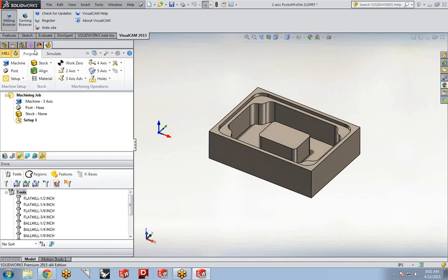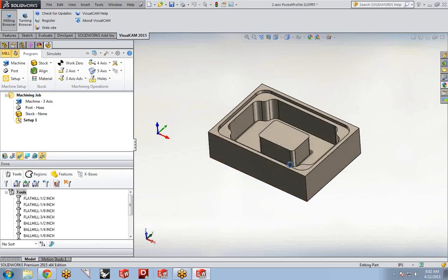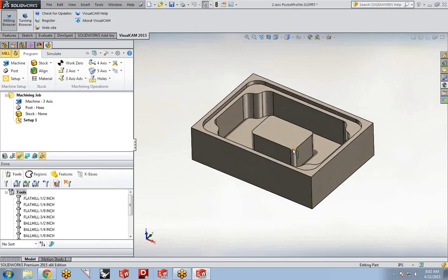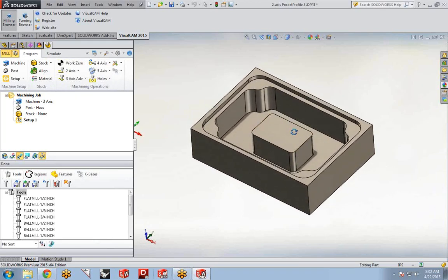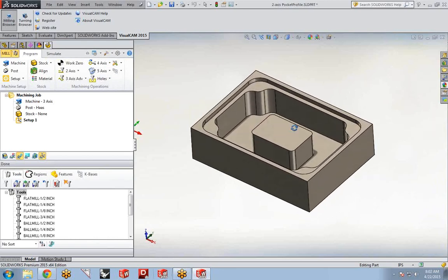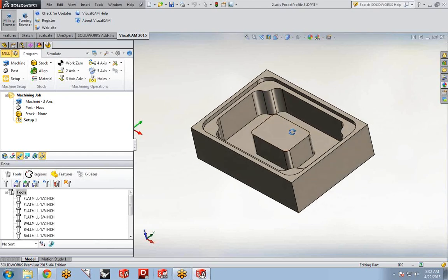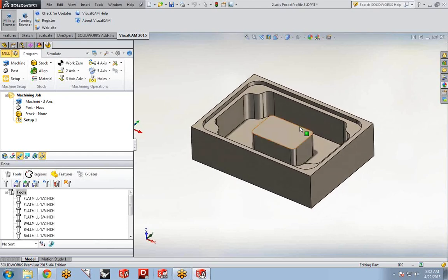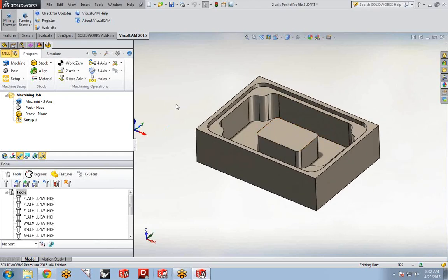First, we'll go up to the Program tab and we'll program the part that's currently designed in SolidWorks. Now, as this part that we modeled is prismatic in nature, where there aren't any sculpted bottoms or drafts on the part, parts like these can be easily programmed using 2-axis milling, also known as 2.5-axis milling, where the Z remains constant as the cutter travels in X and Y.